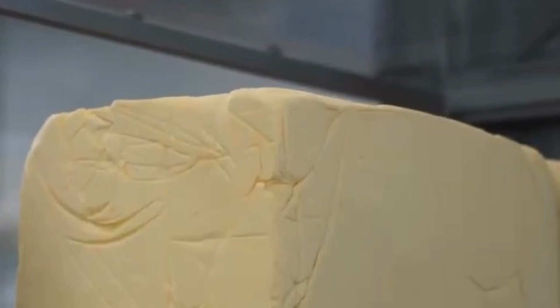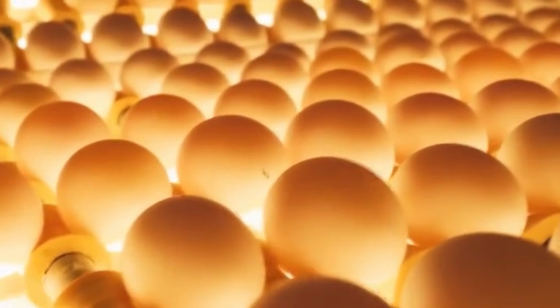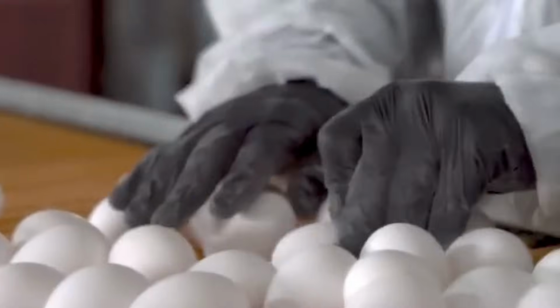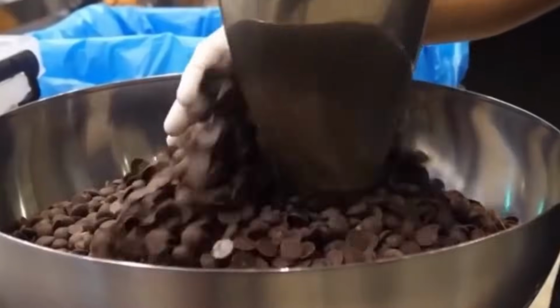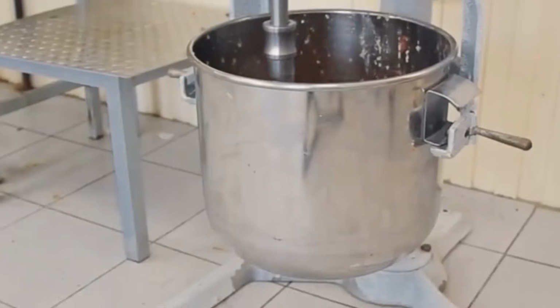These dry ingredients are stored in silos or super sacks and automatically dispensed via auger-fed feeders into high-capacity weigh hoppers. Load cells measure each ingredient to exact tolerances before being discharged into the mixing system.